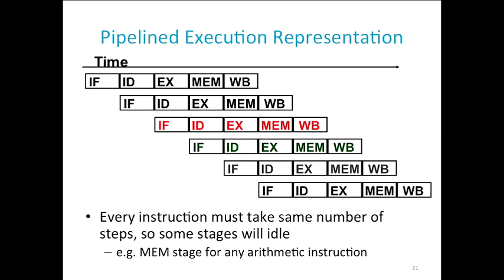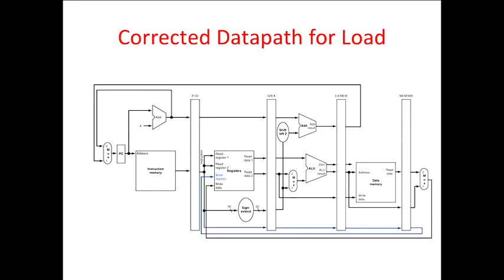Yep. On the last slide, how do you keep track of the instruction or the control bits? So the question was, how do you keep track of the control bits? Well, you capture them here. So when you fetch them from the instruction memory, they come into this register. Then what's happening here is I'm explicitly capturing those in more bits. There's more register bits needed to carry that instruction down the pipeline along with the data as you process it down the pipeline. So you're keeping track of what was that instruction. And as you go down the pipeline, you use the local version of the instruction register to decode and control things. So you have the right instruction going along with the right data. Just keep them paired all the way down the pipeline.